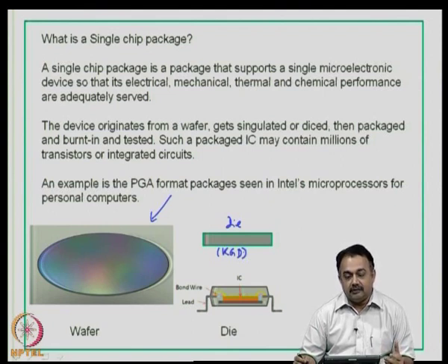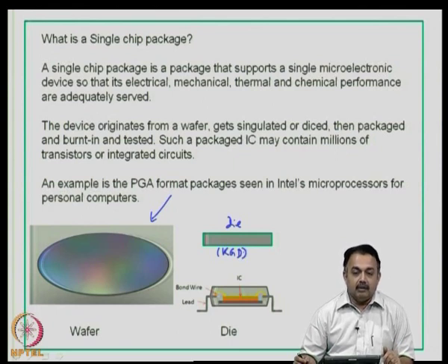we are going to look at what format or form this particular microprocessor die is going to be available in the market, whether it is going to be in the form of a lead or a pin or a solder ball. Okay? Normally for microprocessors it is going to be packaged, but for other prototyping applications this packaging sometimes may not be done. So, it can directly be mounted onto your second level system, which is the printed wiring board. So, that is known as a bare die.